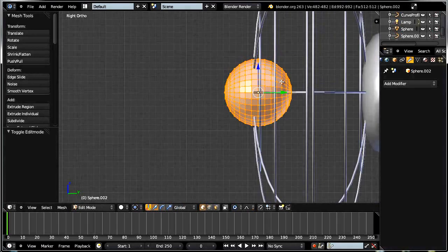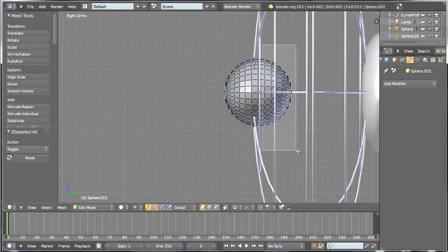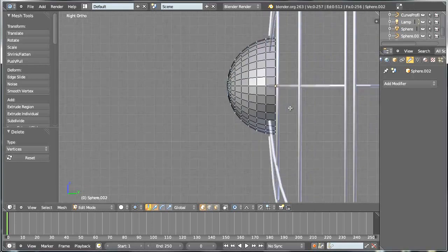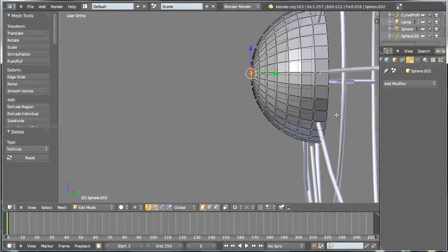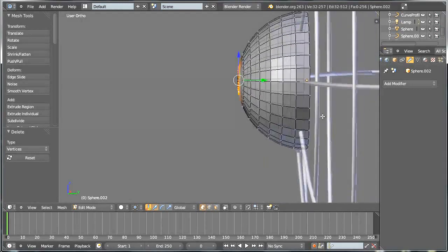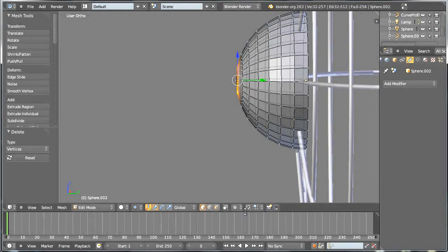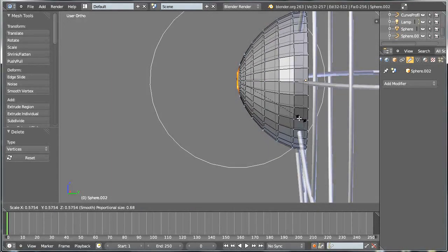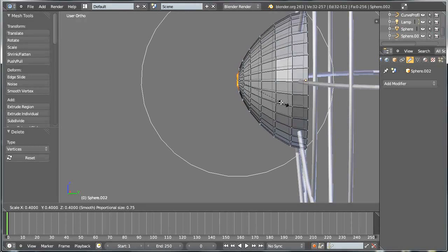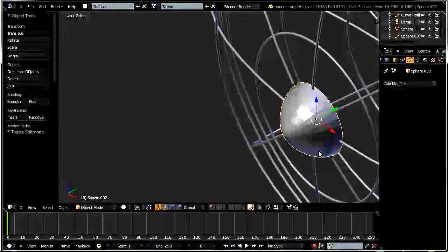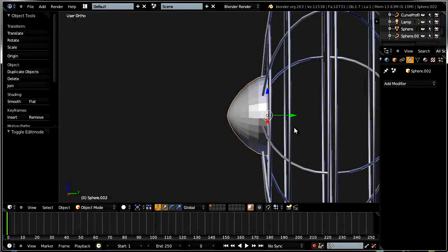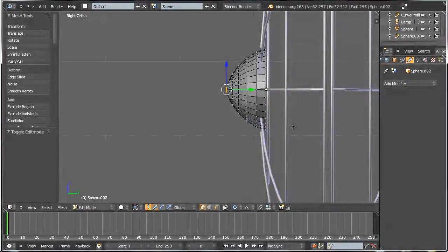here, right? And now tab into edit mode and border select those vertices, and just go ahead and delete the vertices. And now I can always select this vertex, and by pressing Alt+O and also selecting this loop here, enabling the proportional falloff, scale this down a little bit, so I'm giving it this kind of pinch here, which is usual for fans. Alright, for typical fans.